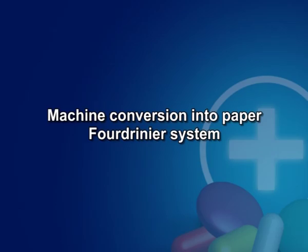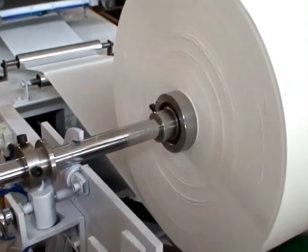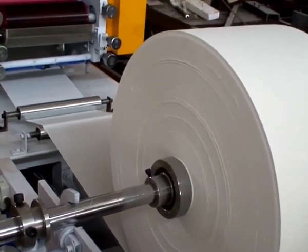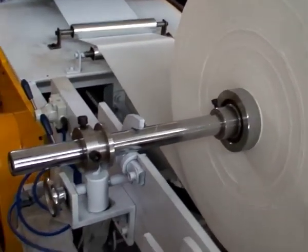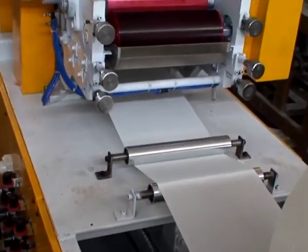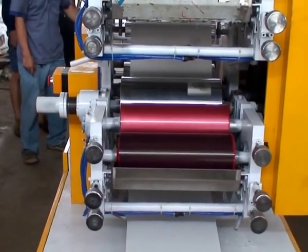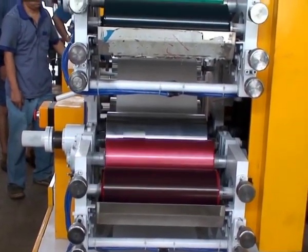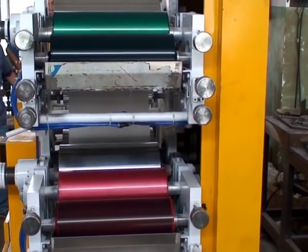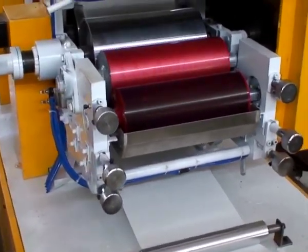Machine conversion into paper, Fourdrinier system. This is the most popular system still used today, even though the basic system was invented in the early 19th century. Pulp, including all the additives needed for a particular paper, in suspension is pumped into the stuff chest, then let down. The machine starts at the wet end, parts 1 to 4, and finishes at the dry end, parts 5 to 9.